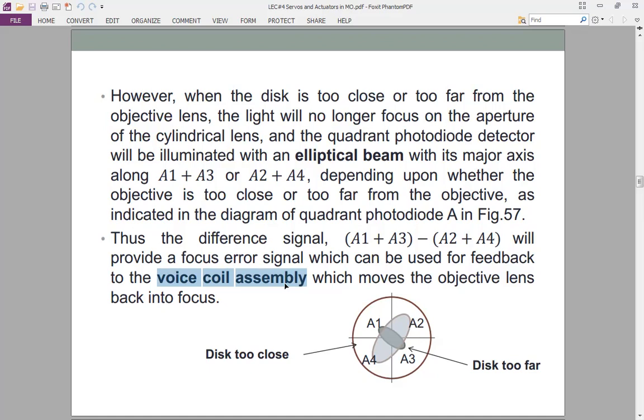It is the same scenario here. The only difference is we do not have a fast varying current. For example, if the disk has moved too far, it may send a positive error. A positive error would mean that maybe a current of 0.1 is sent to the voice coil, and when the current is sent, there will be a force that will push the coil maybe outwards.